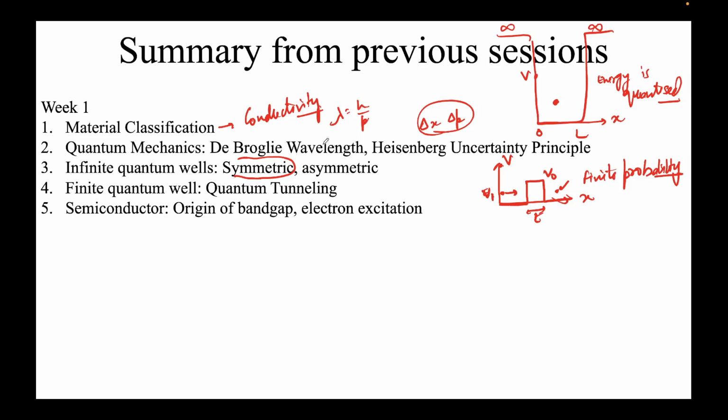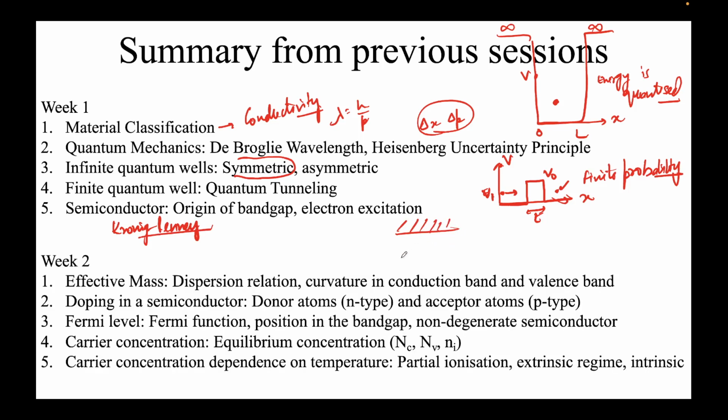And then we condensed all this information of quantum mechanics into a lattice, which is essentially a collection of atoms periodically placed. Each atom, because it has a nucleus and electrons, will have its own electric field. When we bring them together, their orbitals overlap. There are different ways of seeing that, and then we modeled it through something called the Kronig-Penney model. When they come close together, their orbitals overlap, and we get something called a band. By that I mean something like this.